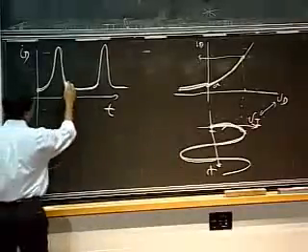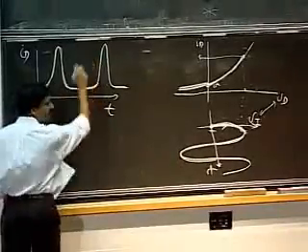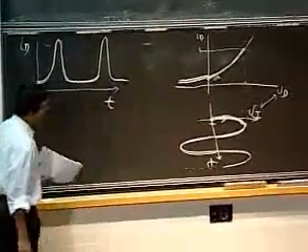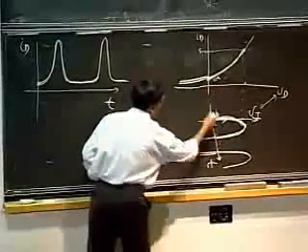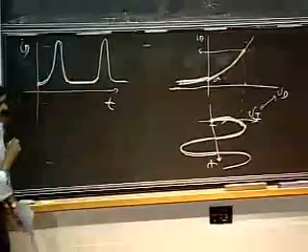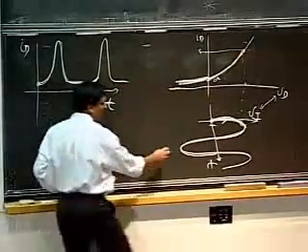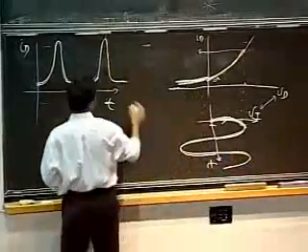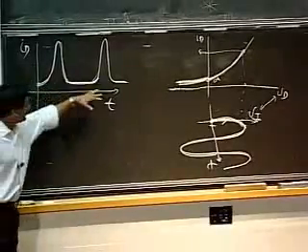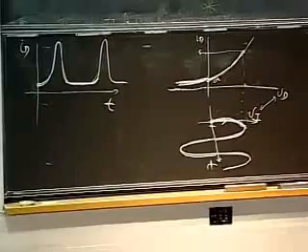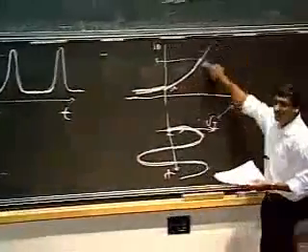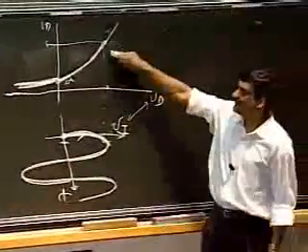Rather than giving me a nice little negative spike excursion here, what this is doing is that it's taking this excursion and simply slamming it down to this value here. And then again, when I go back up, I get this peak here. So notice that what was a nice little sinusoid out there gets hammered and squished into this funny curve here. What this device is doing is for positive values, it tends to produce exponentially greater current.